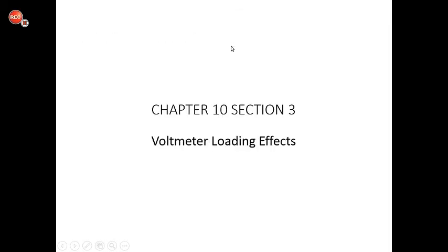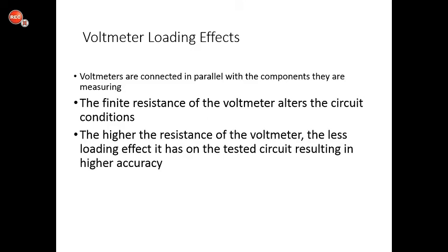Section 3 is about the voltmeter loading effects. And again, we covered this in DC circuits. We'll review some problems here in just a second. Voltmeters are connected in parallel with the components that they are measuring.